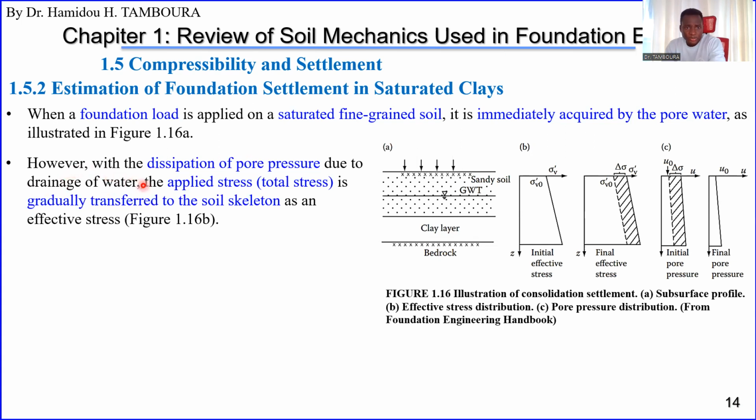And then during the dissipation of the pore water pressure due to drainage, because the water will drain, but very slowly. While the water is draining, the load will be transferred from the water to the soil particles, okay?